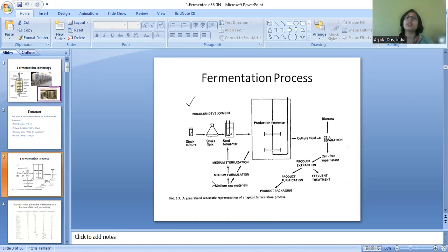Along with that, you have to take care of foaming. Certain anti-foam should be added there so that foaming can be reduced. The antifoam agent should work in a manner that it should destroy the existing foam and it should hinder foam formation. So it should work in both ways.